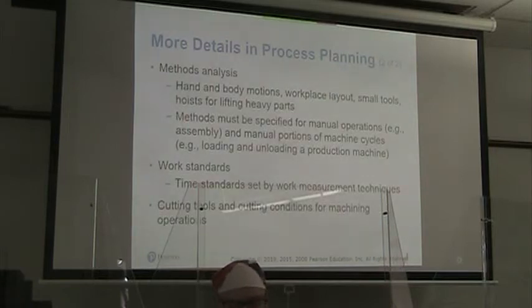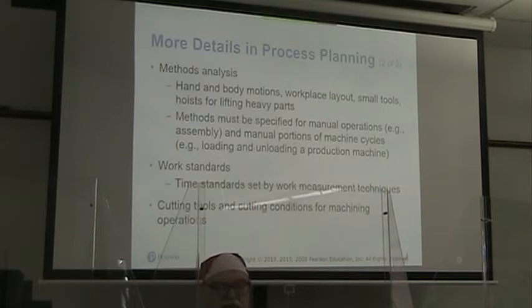We want to set work standards, so setting those time standards using work measurement techniques. And we want to see what we need to do as far as cutting tools and cutting conditions for the machining operations.